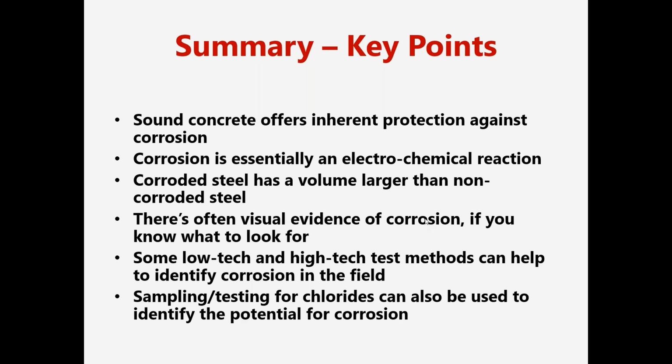You can see it a lot of times if you know what to look for. It can be pretty obvious sometimes. There's some high-tech methods, some low-tech methods to help identify corrosion in the field. A lot of them are related to sounding, either electromechanical sounding or just physical sounding with a hammer or a chain or something like that. And then different methods of sampling or testing for chlorides.